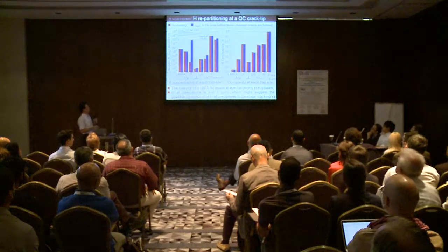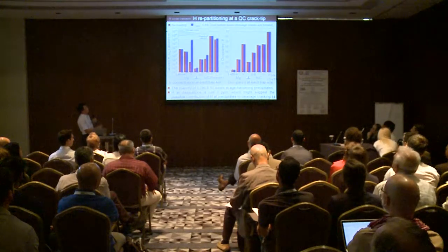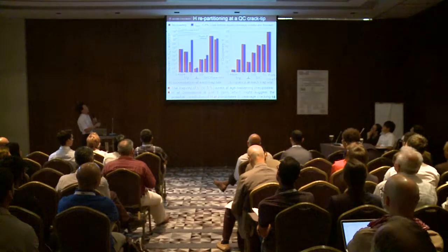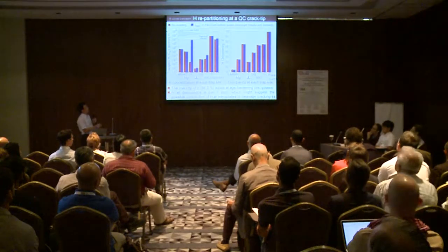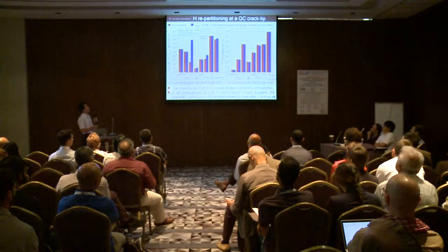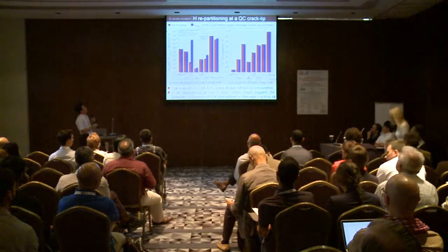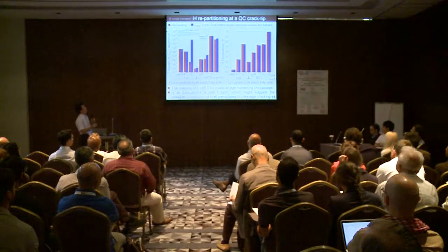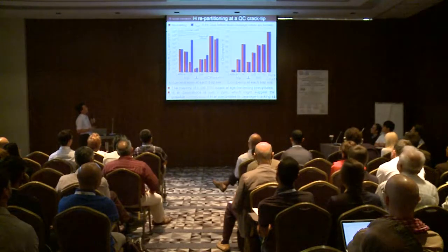Then we identify the region of interest here and then calculate the partitioning of hydrogen in this localized region. So we have various hydrogen trap sites, and this is trapped hydrogen concentration, and this is hydrogen occupancy for each hydrogen trap site. And blue bars are the data after deformation of 4.4%. Red ones are no loading data.